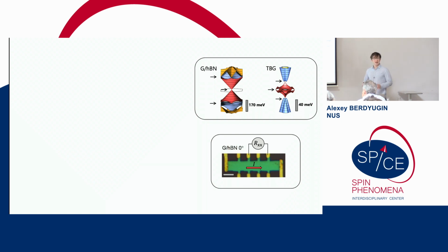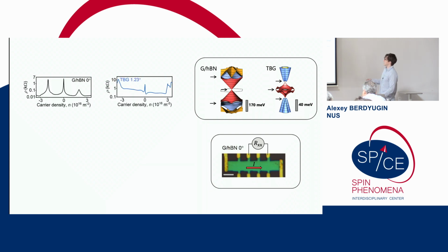Our experiments actually are super simple. I'm sure that everyone with proper graphene devices can do it. To study the nonlinear transport, you simply need to take a conventional Hall bar and apply current. That's all you need. To begin with, we studied and characterized our Hall bars in a linear response regime and saw that they're indeed completely usual.